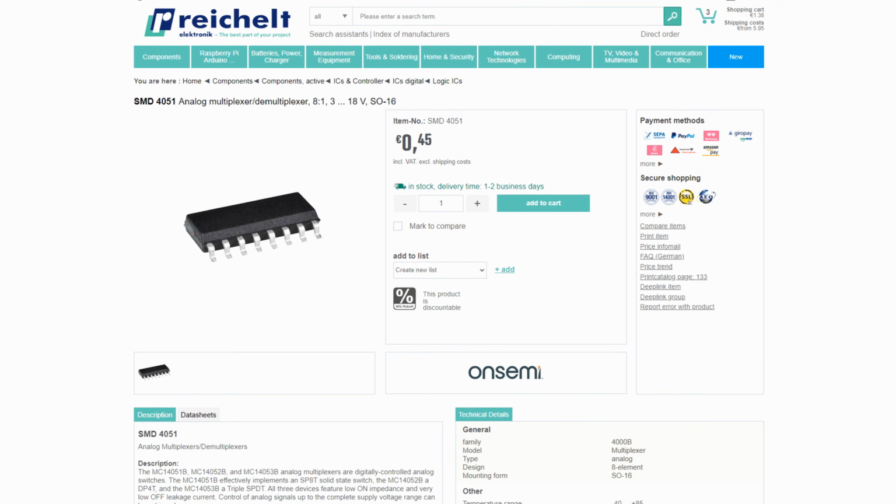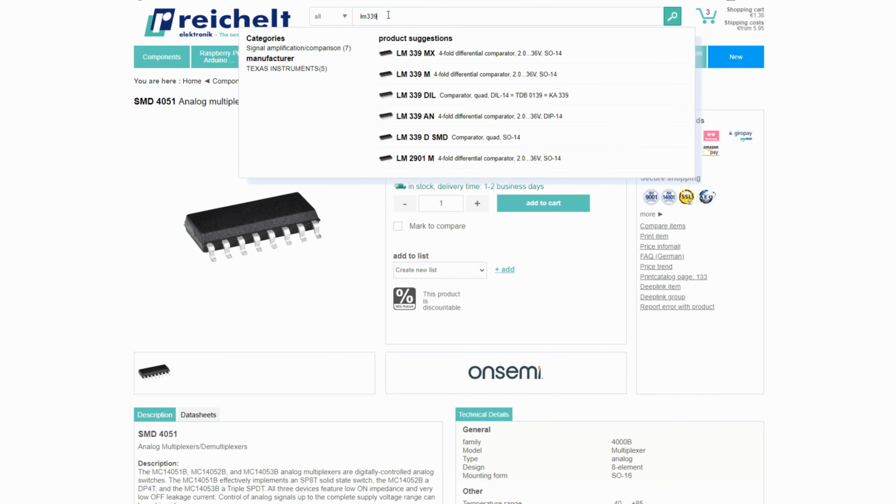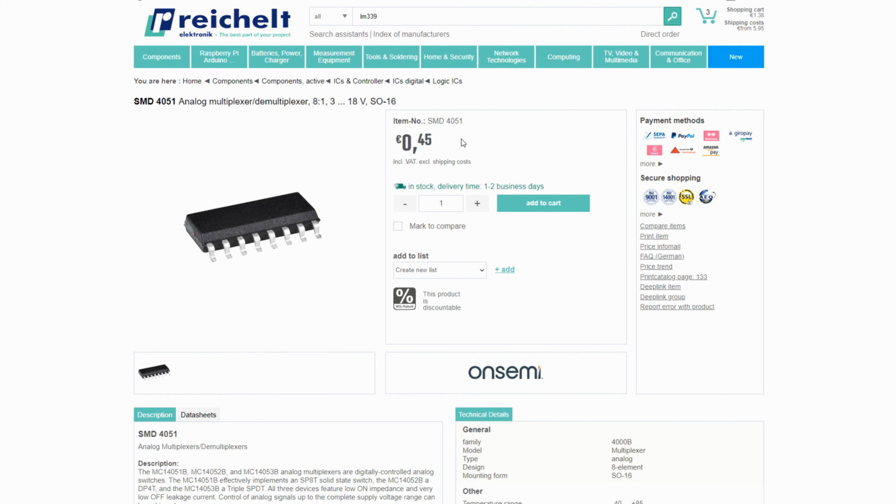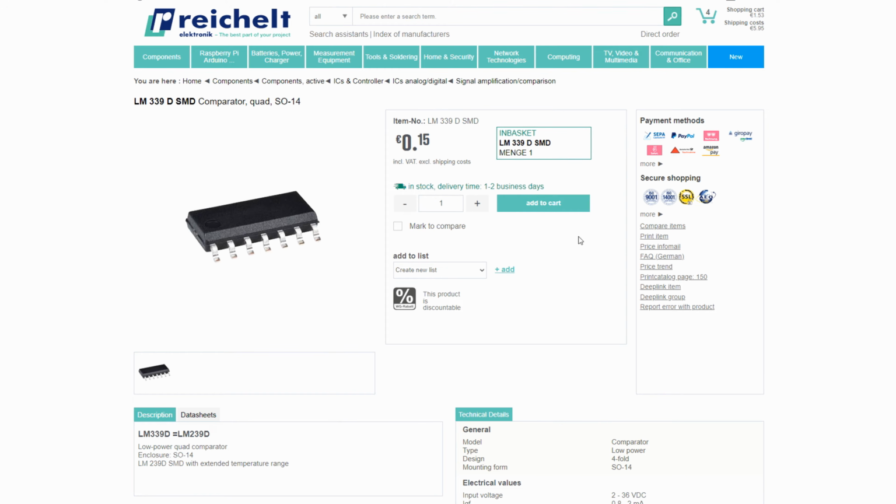If you ask me, that sounds highly suspicious. And finally, 74HC595 is a shift register, which in short words can store and transfer incoming data. I don't think that this part is faulty, but as these parts are cheap, let's order one anyway. And I also ordered replacement potentiometers, and that's it.